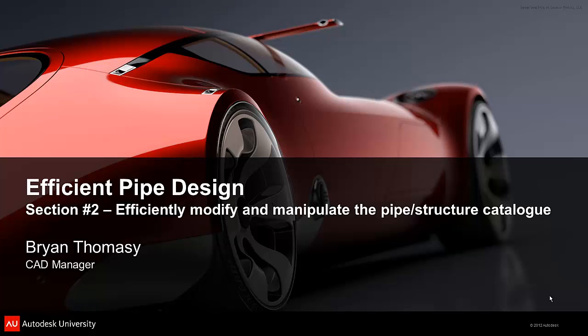In our previous section, we generated a couple of part families, one for our rectangular parts and one for our valve parts. So in this section, we're going to be adding the dimensions to these items so that they appear in model space correctly.